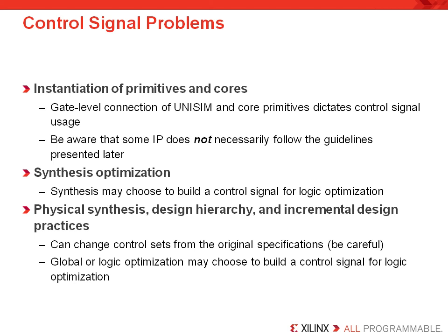Likewise, if your design is large, plan on evaluating your synthesis results as early as possible, and always take the time to verify your synthesis tool generated the anticipated and appropriate control signals for your application.